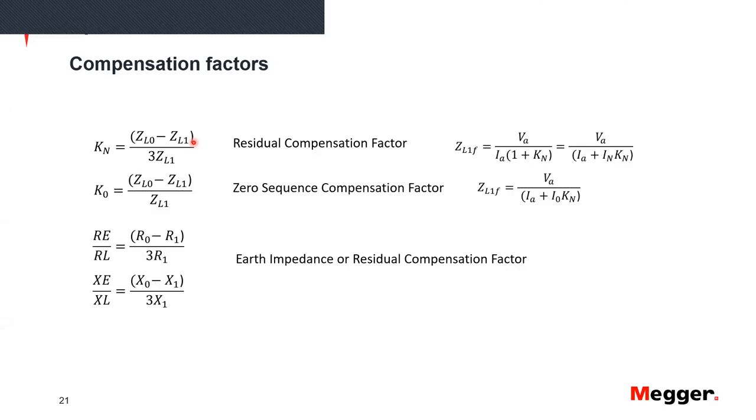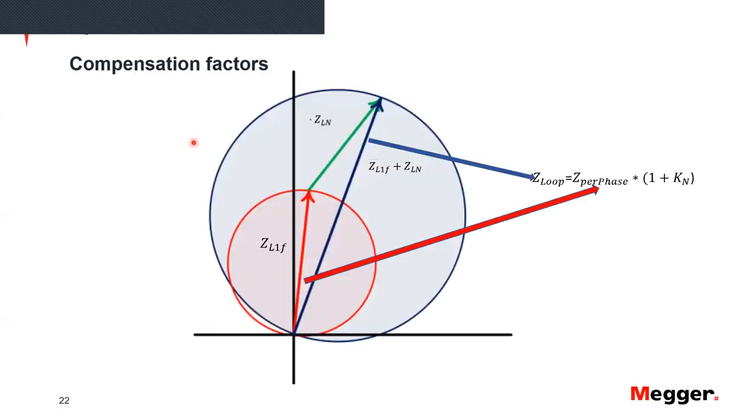Now, different relays will have different compensation factors, and the idea is that you have to learn how to use them, and you have to understand what those compensation factors are. Now, I'm going to show you here a diagram that, in my opinion, connects what the compensation factor means and what it means for our impedance protection, and especially later for our impedance testing.